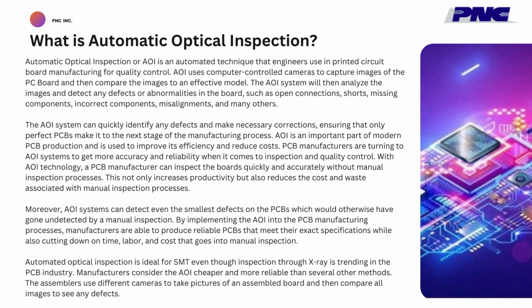The AOI system will then analyze the images and detect any defects or abnormalities in the board, such as open connections, shorts, missing components, incorrect components, misalignments, and many others. The AOI system can quickly identify any defects and make necessary corrections, ensuring that only perfect PCBs make it to the next stage of the manufacturing process.